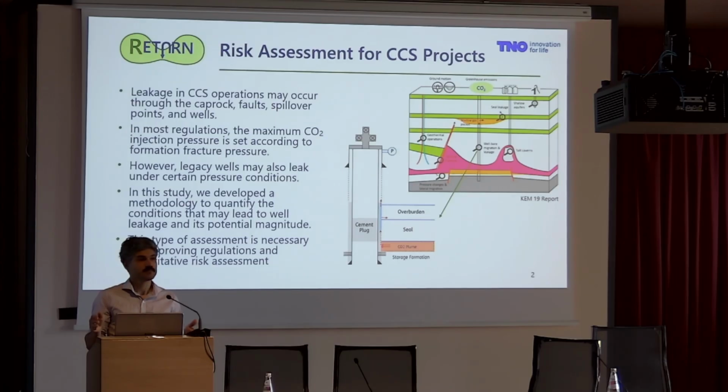Now, in most regulations that we have so far, usually the pressure of a system is set according to your caprock or reservoir fracture initiation pressure, some form of that, and then you have a factor of safety added to it. So this is the standard practice. However, when we come to CCS, we argue that for the pressure budget we need to also include the wells.